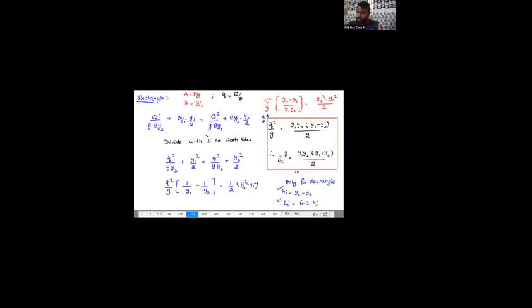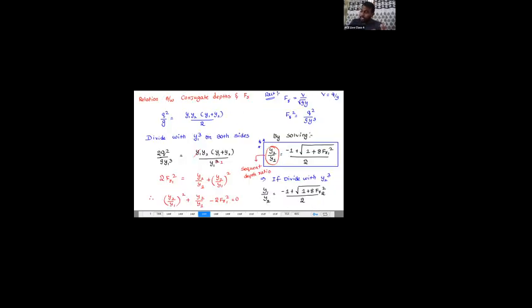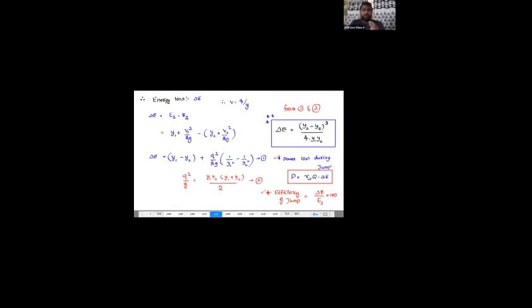So, in simple words, what I want to conclude is, if the inlet Froude number is more, then the ratio y2 by y1 is more, which means the difference between y1 and y2 is more. When the difference is more, the energy loss is more.